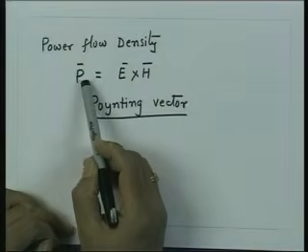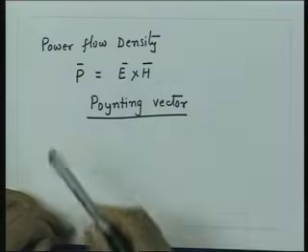So, Poynting vector, which we define as E cross H, serves the purpose of defining the power flow, but in a practical system, a more useful quantity will be the time average value of this Poynting vector, because if I take some instant of time, first of all this quantity may even go negative. So, if this is telling you power, it may even give me negative power.